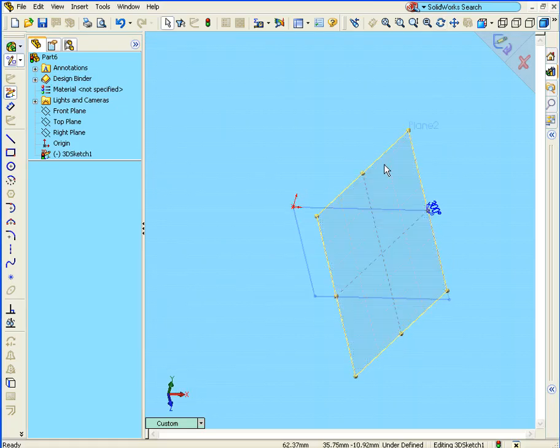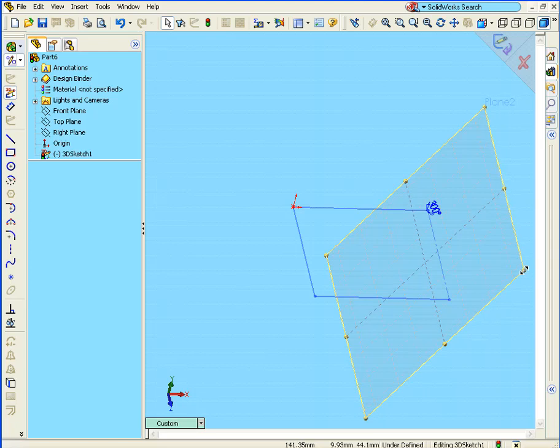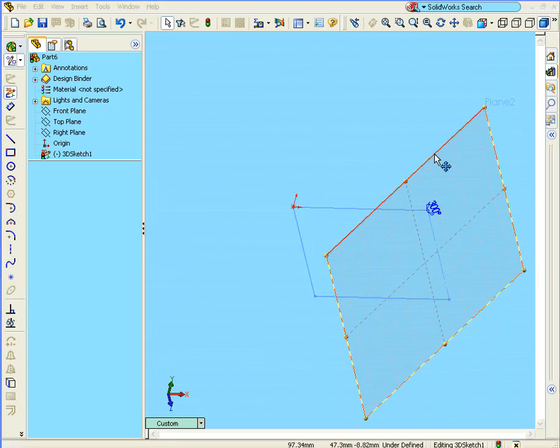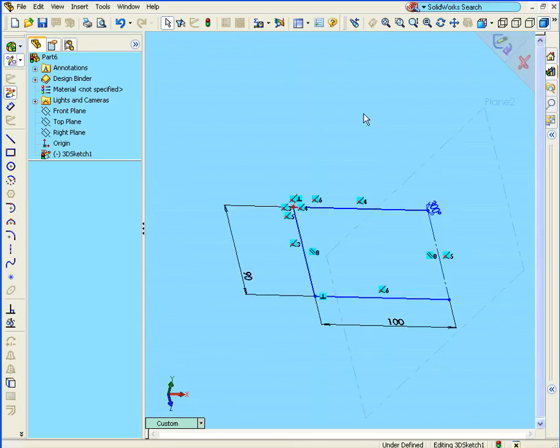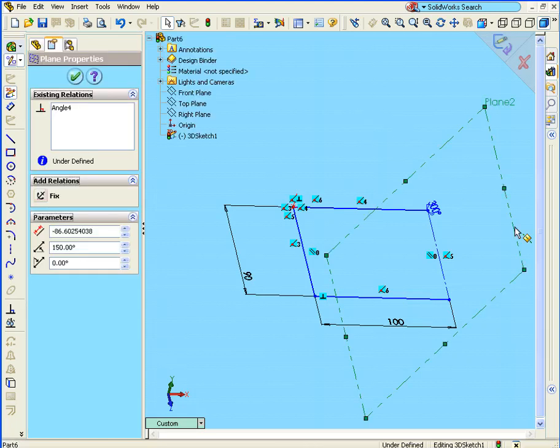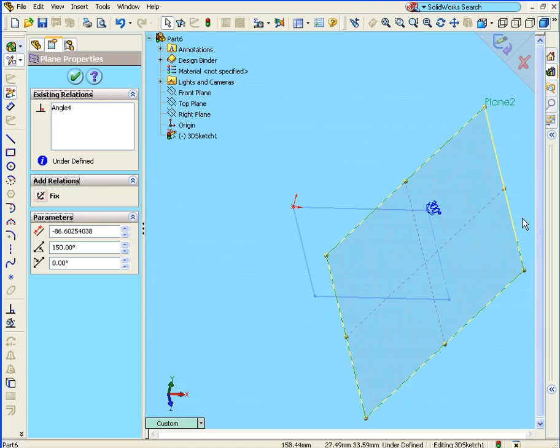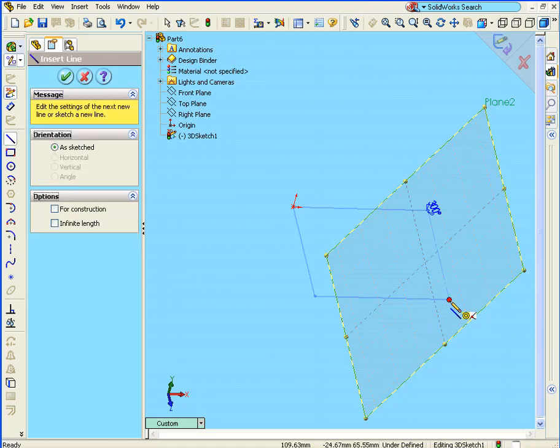Let's continue with our sketch. We can resize the three-dimensional plane by dragging these handles. And like you see, the 3D plane is currently active. To deactivate this plane, double-click in the graphic area. To activate it again, double-click on the plane. I'm going to select the Line tool now and continue our drawing.